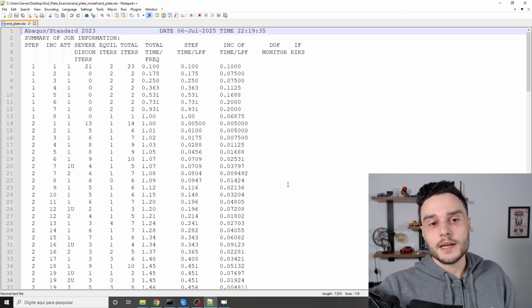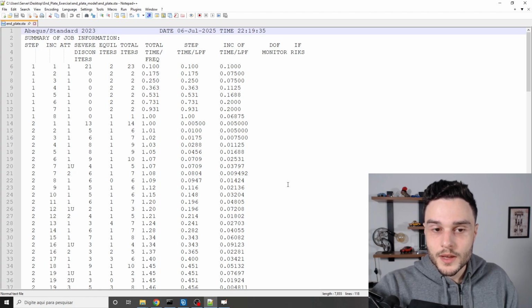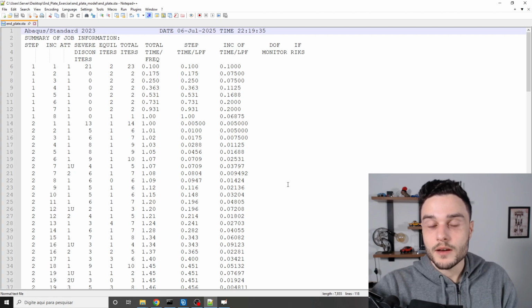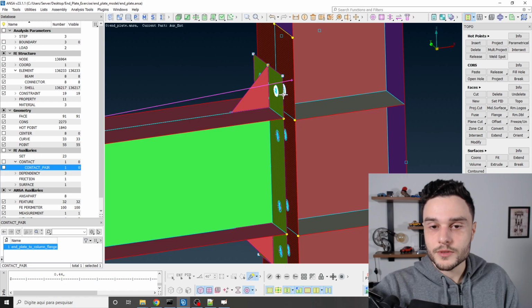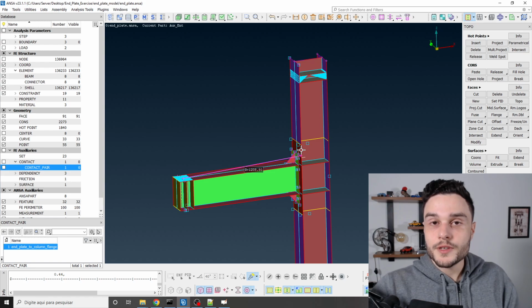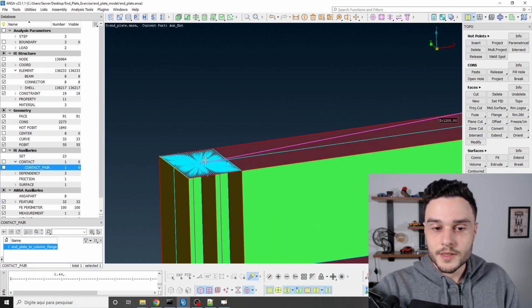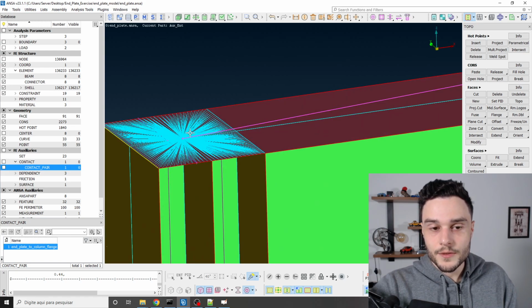Guys, remember that in a non-linear finite element analysis, the stiffness varies while we apply the loads, the external loads. In this case, we have a displacement applied here, and the connector loads, and also the body force, which is gravity. So these are the loads. Even this displacement is a load because we know that this is going to yield a reaction force. So we can think about it as an external load that is being applied.